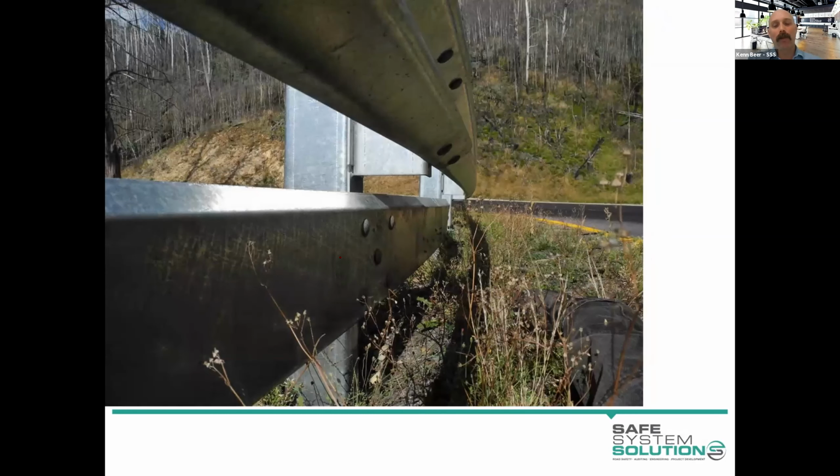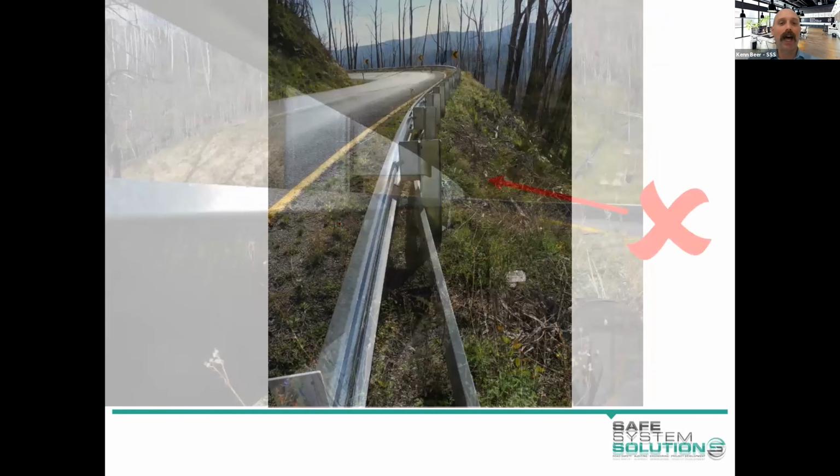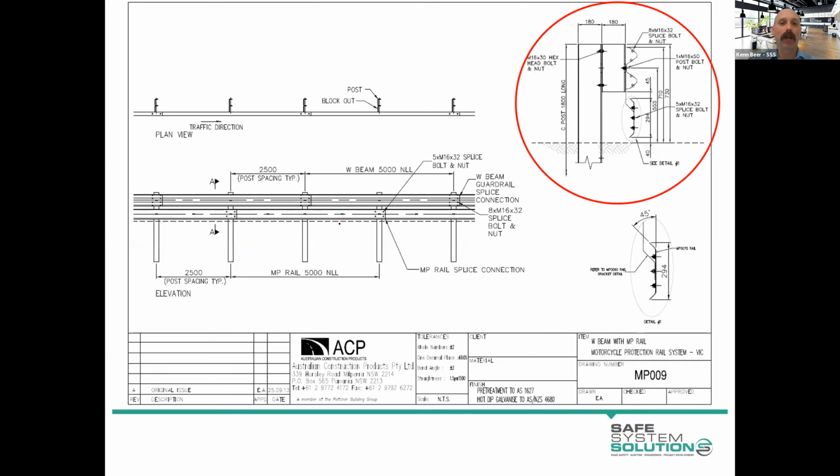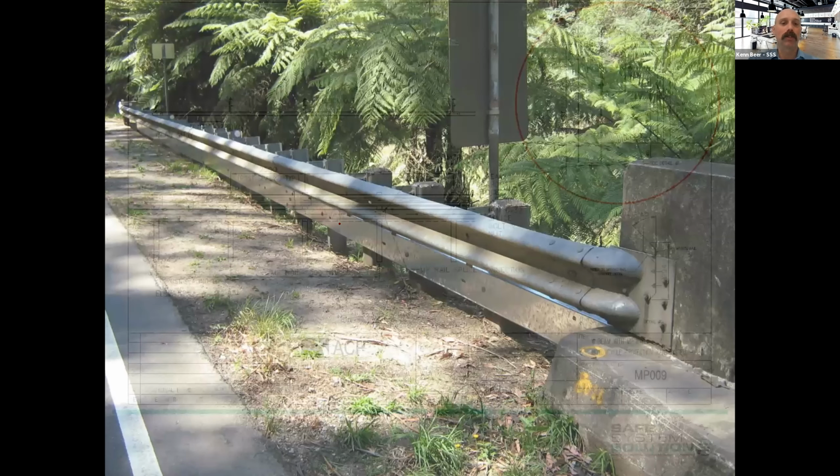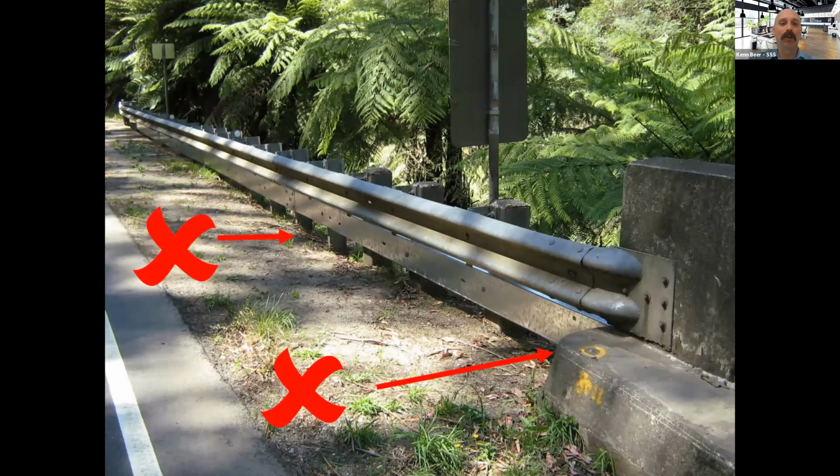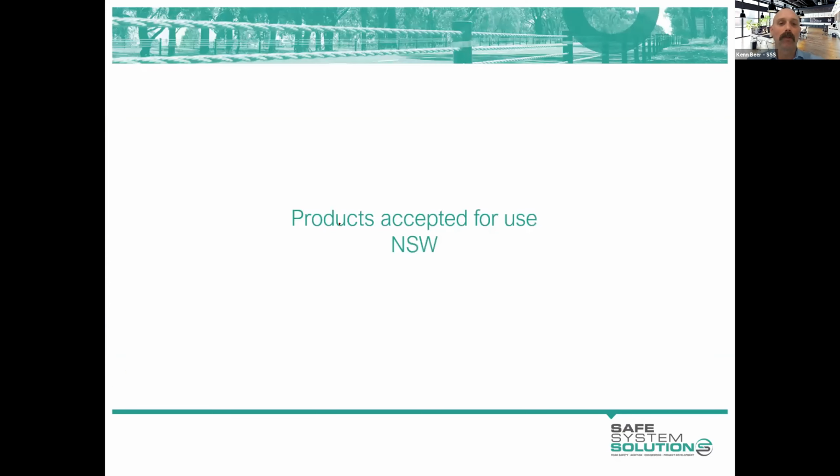And just be careful about any retrofit installations that they're done right. People like to attach them to the post, and that's not correct, because you can get an arm and a leg through there easily, and that'll happen. Check the product descriptions. Any gaps or anything that you can run into, obviously things that you want to rectify.